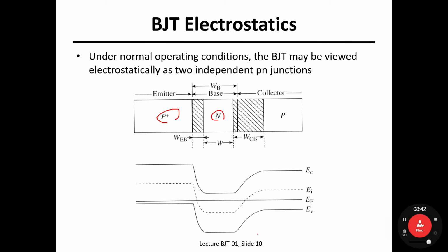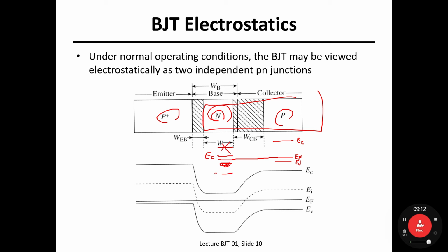Now it is the turn to draw the energy band diagram for the base collector junction. So this is another PN junction. As we have learned, here is the P side, E F, E V, and this is the N side. So E F is single valued. The conduction band is very close to the Fermi energy level, and the valence band is here. So maybe the band bending can be drawn like that. You can clearly see that in my energy band diagram here.